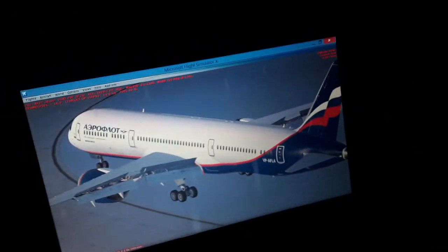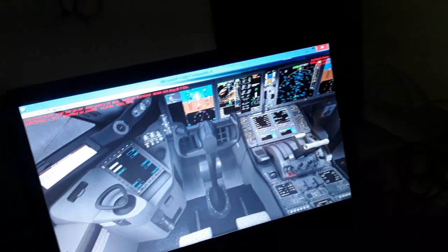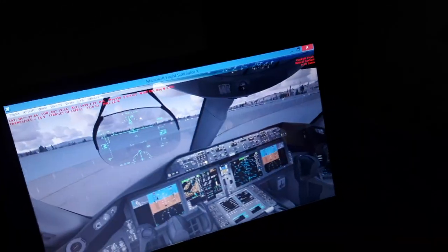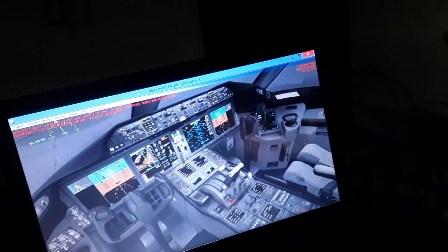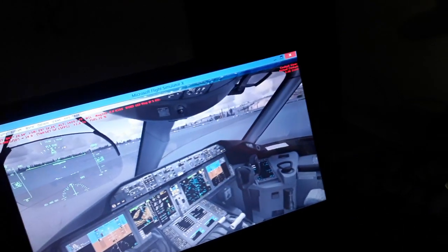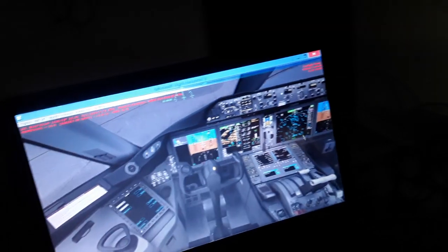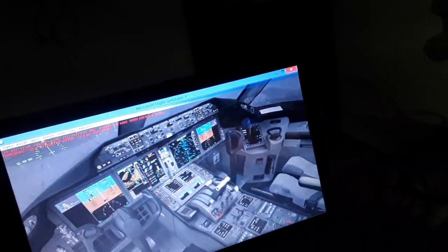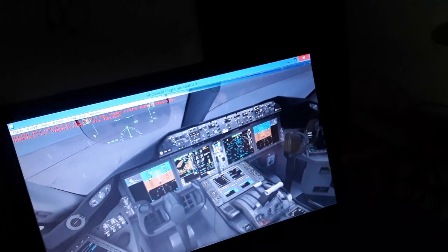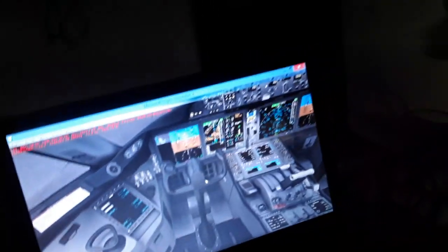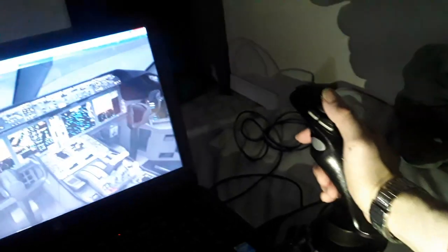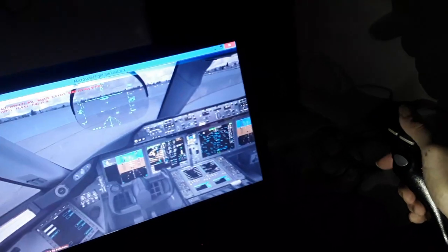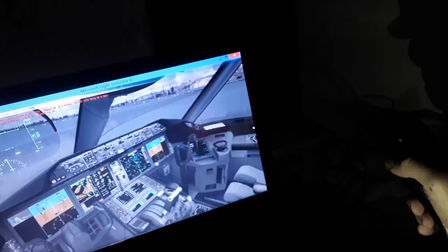So you can see we have the nose wheel steering here. It controls up to 76 degrees usually of left and right turns. Also we have the rudder pedals for doing that, interconnected on the ground. It controls lower, to like 7 degrees maximum deflection above 45 knots in takeoff, because we have the rudder also dynamically effective from about 45 knots and higher in takeoff.